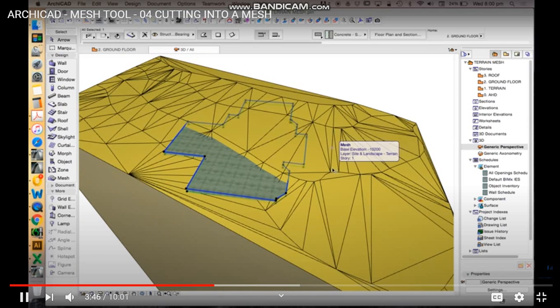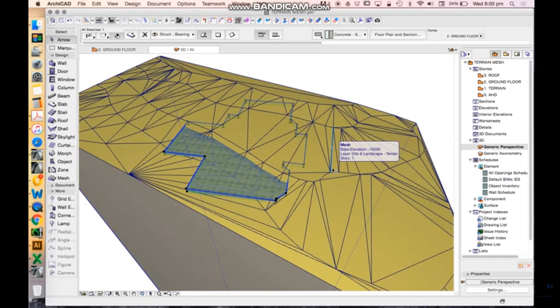Yep. So in real life, a slab could be doing this, but normally, in a real life situation, we would have had to excavate that site first. We would have had to dig it out. Now on a site like this, we could completely excavate, or we could do cut and fill, where we're cutting part of the site and filling part of the site to try to get the slab sitting at a median height, or we could build up the entire site, so filling the entire site.